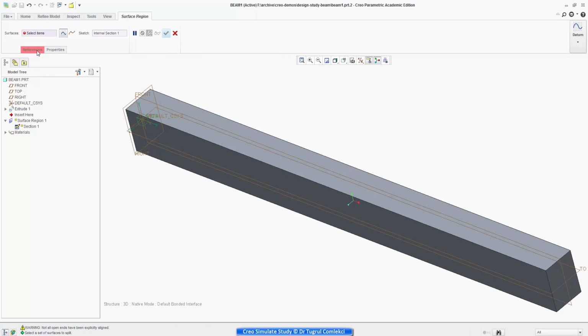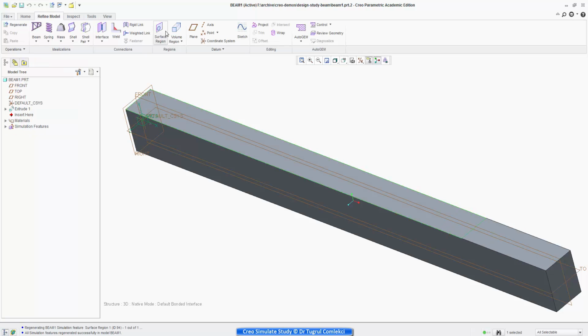And I want to then define the surface that has to be split by this simple line. So that's the line projection again. Let's say okay to that. So now I've got two surfaces where I can apply some surface loads. So if we do a basic analysis now, I just want to show you that you can apply some more controls to this.